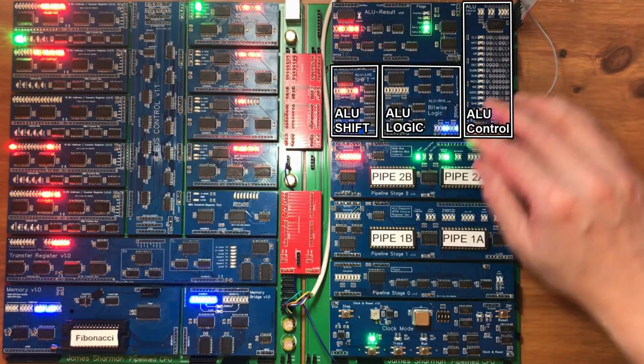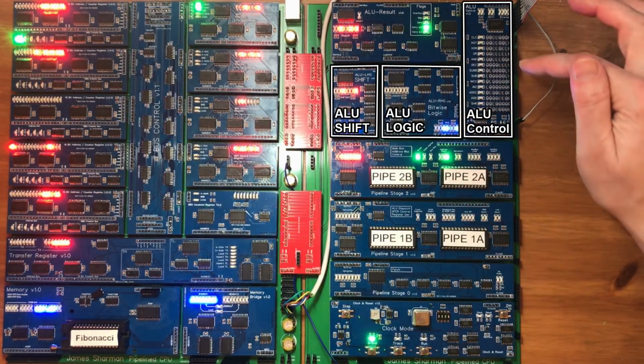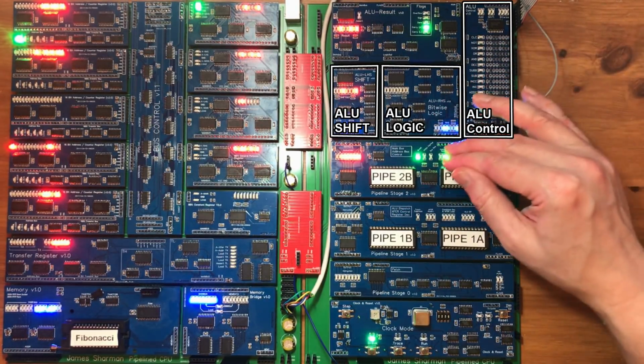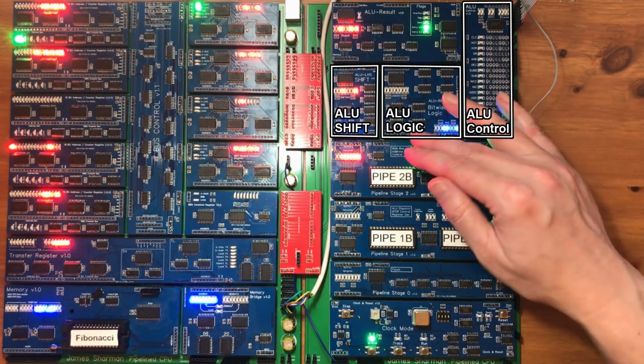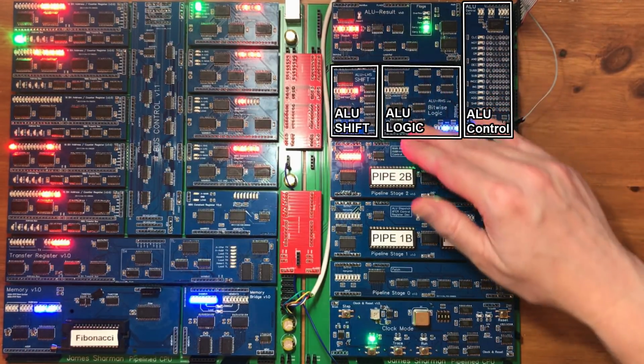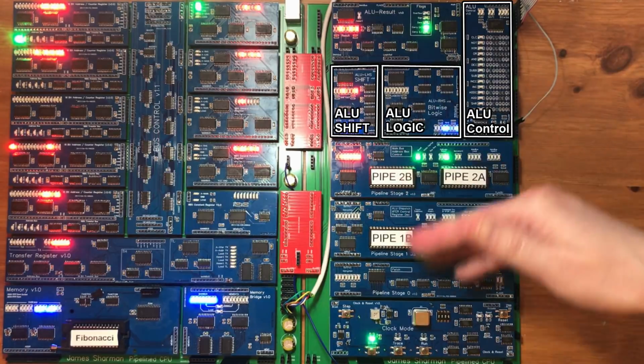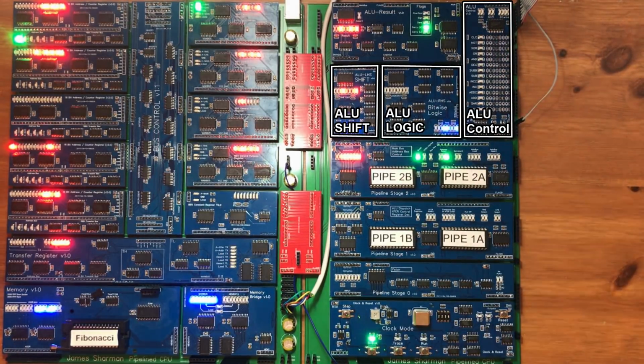And what that basically has is 4 bits coming out of the control, which is a 4-bit lookup. So I can basically reproduce any bitwise operation here, or it can also output a 0 or just an inverted form of the right-hand input.